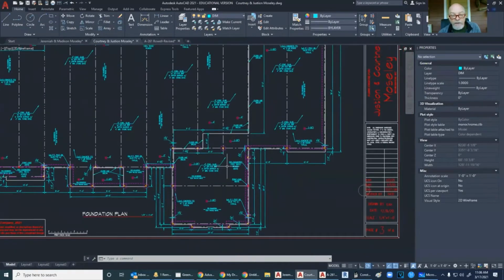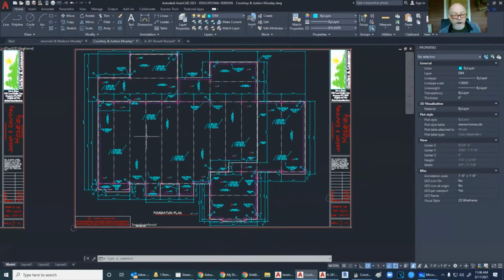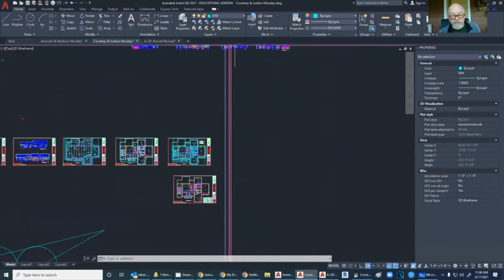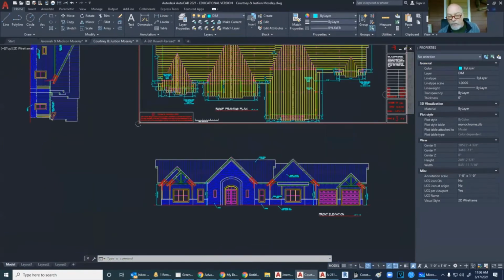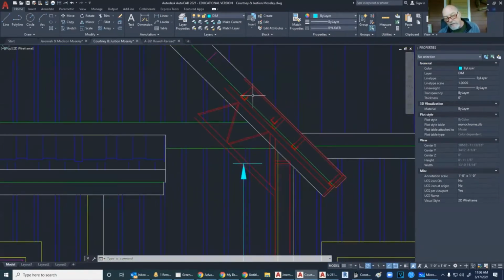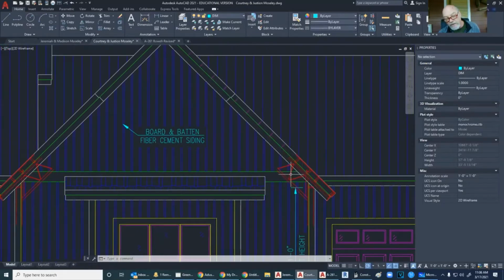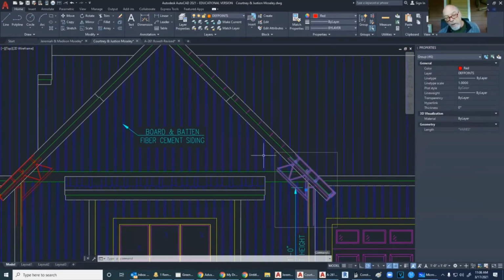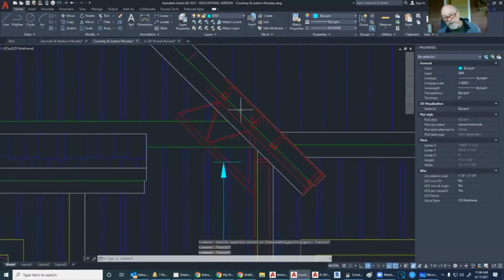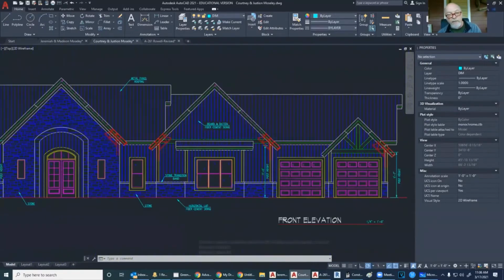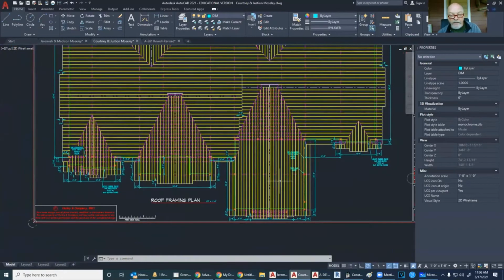And so, if you get one of these posts wrong when you're trying to frame this, then when you get to this monstrosity, and I'm telling you, this has driven me nuts because I've only done this twice before, and it's a different thought completely because these actually run in a different direction. You're using the truss as the support, and you're putting purlins in at 16 inches on center or 2 foot on center to hold your plywood. And so to draw that is freaking crazy.